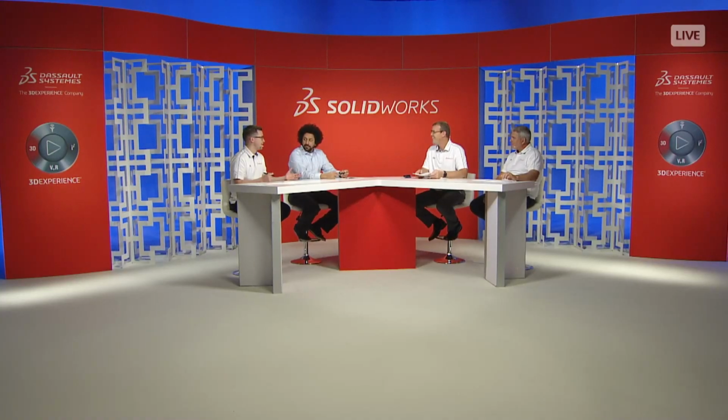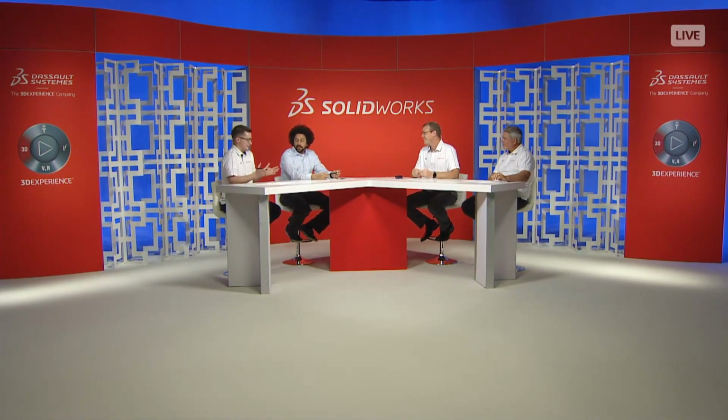Omar, how long does setting up something like this take? From I have the initial CAD model, I made it in SolidWorks, from the initial design to the optimum design. Yeah, so setting up the DOE and figuring out the ranges for those variables, maybe it takes 30 or 45 minutes, and then it's got to run each of those individually. That may take an hour to run those. I think there were 40 steps. It probably takes less than that, actually. But within 2 hours, you're getting an optimal design. This is just looking at temperature. Obviously, if you had stress constraints or frequency constraints, you could couple all those together and do a multi-parameter optimization. It's a really powerful way to utilize simulation.